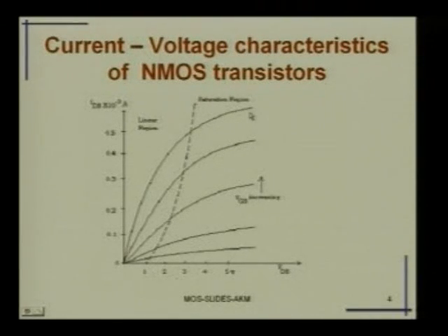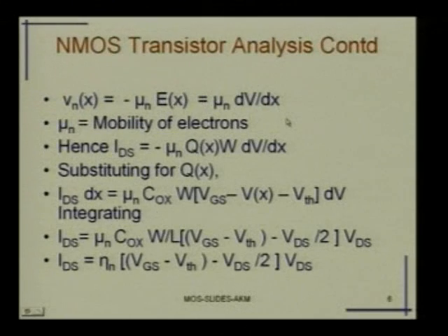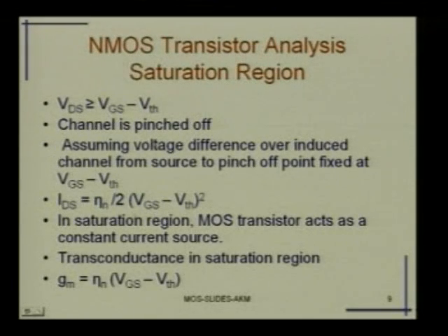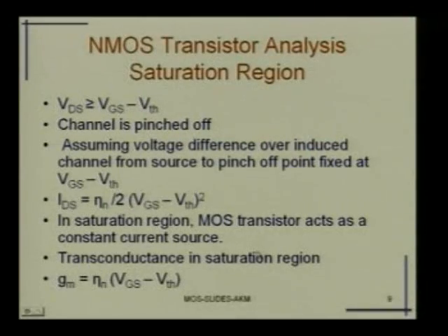Now, you can say that still it is increasing. That part we will see, but effectively if it had been a pure saturation, it should become flat, because in this region there is no increase as we have discussed. So, this is the reason why the drain to source current is proportional to VGS minus VTH squared, and this is called the saturation current region.